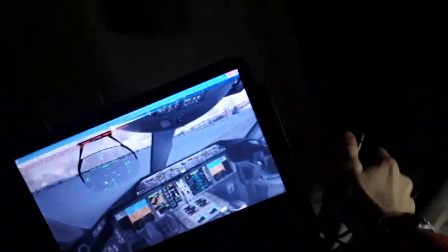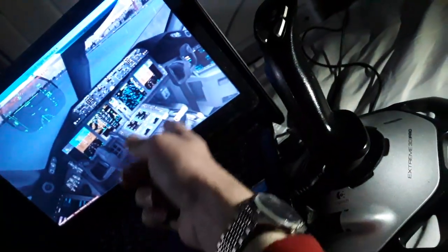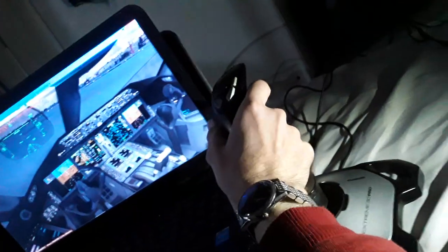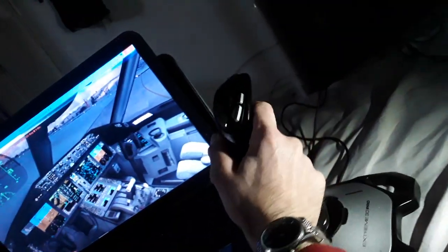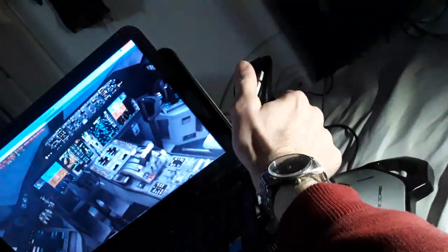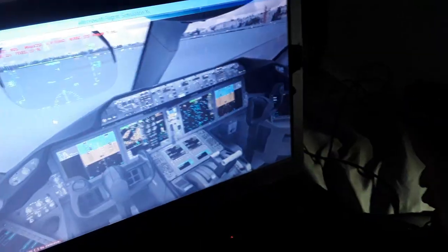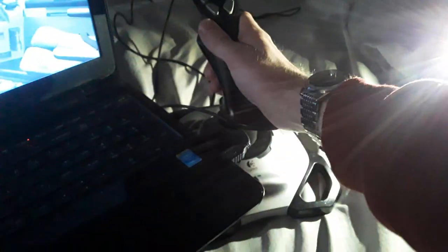We have the horizontal trim stabilizer. You can see both sides, the captain and the first officer, are interconnected and moving together in flight in the Boeing aircraft. So climb, descend, make turns left and right, interconnected flight controls. Unless you have a failure, you can move with an override force in the Boeing aircraft. In the Airbus, you have the side stick priority button over here. You take other side priority in the Airbus aircraft. So in the Boeing you use this system.